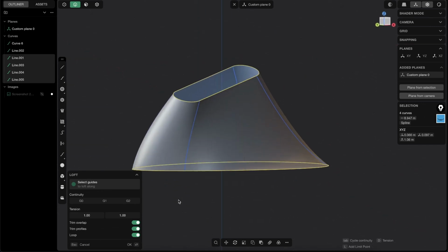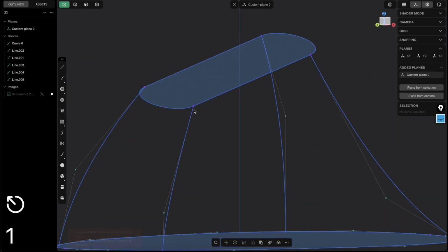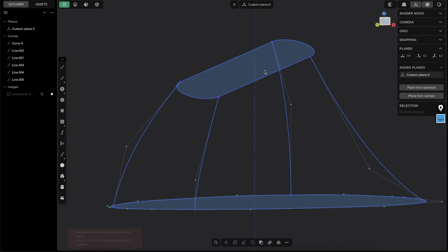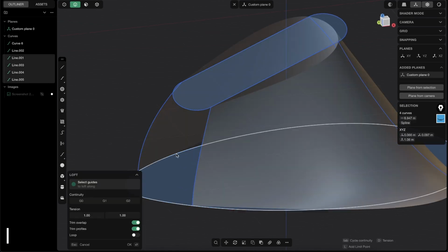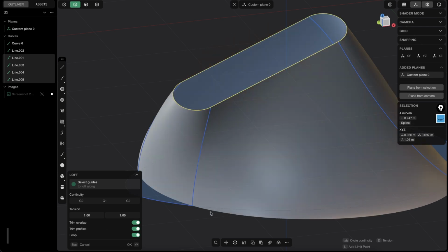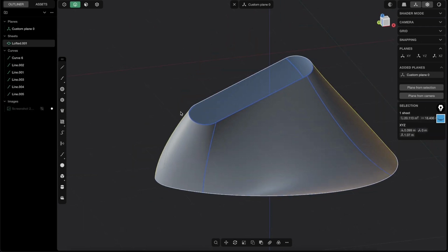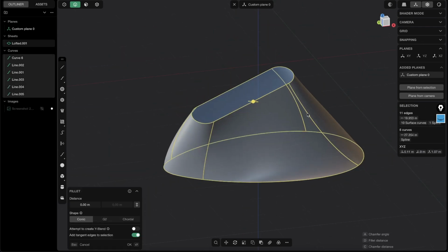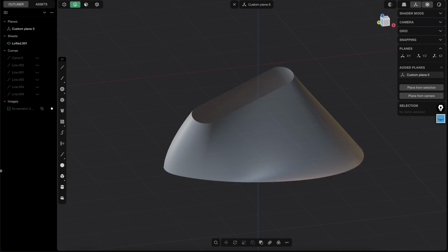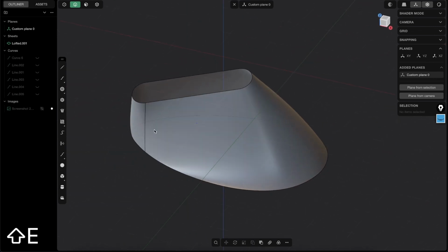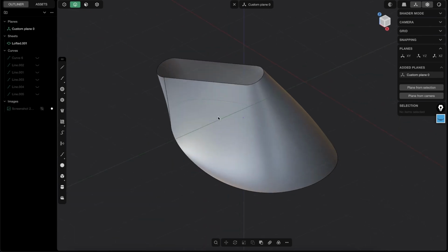And again, if this does not work, it's because some of your curves are not connected. So always make sure every endpoint of the curve is connected. So just quickly again: loft, loop, shift, shift. Perfect. Now press 2 again, select all of those curves, press H just to hide those curves. Never delete them, because oftentimes you will need them later.